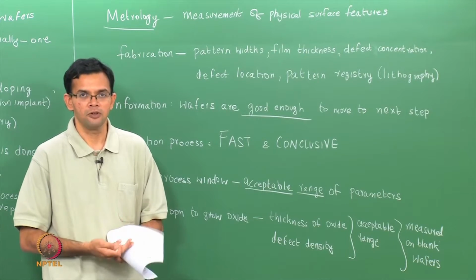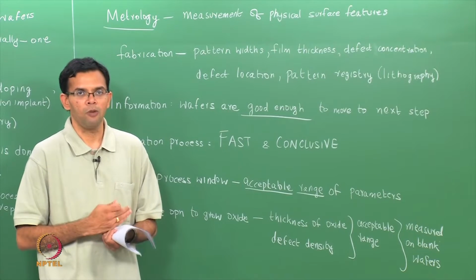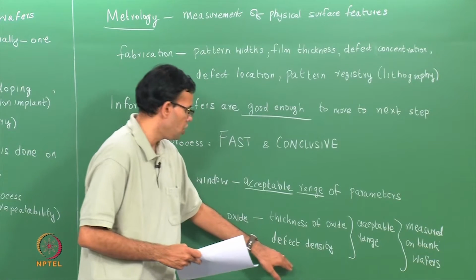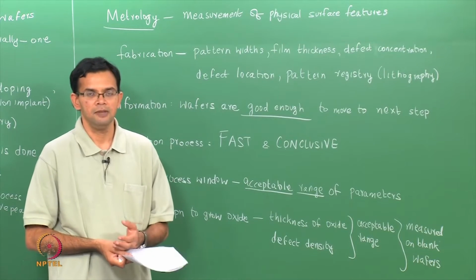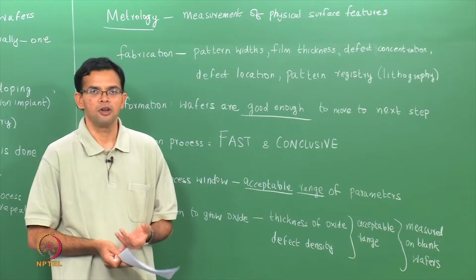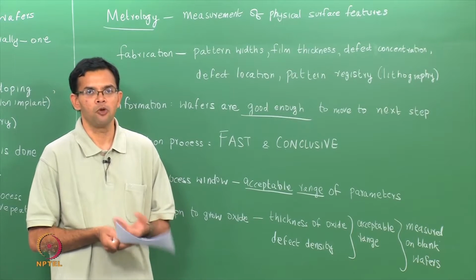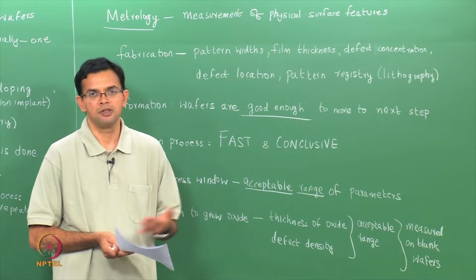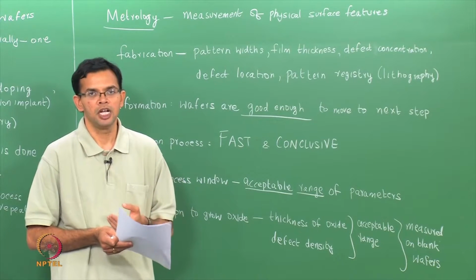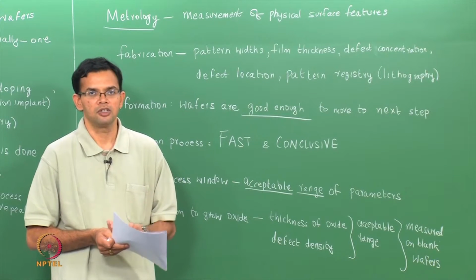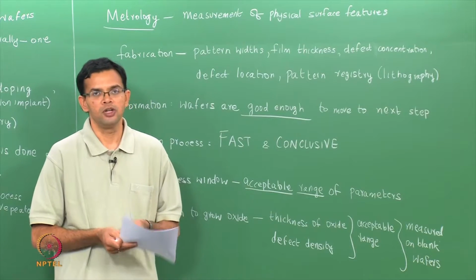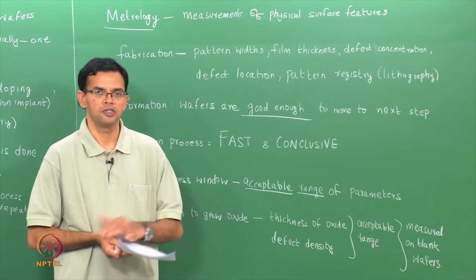The drawback of course is if there is a problem with the process which causes either a thickness shift or a high level of defect density, because it is a batch process you will essentially affect more than one wafer, which means if the wafers have to be scrapped, when we say scrap, those wafers are condemned and destroyed. You will not only destroy one product wafer, but you will destroy multiples of product wafers.